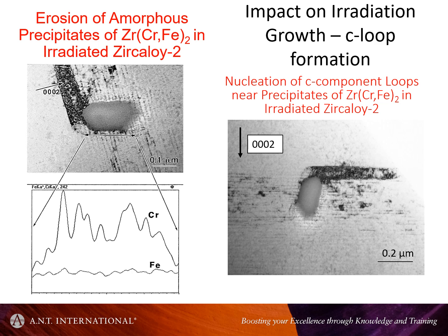But it turned out, to their credit, they reported years later that they found that ion milling created amorphous transformations. Basically, it was an artifact. So just like the hydrides, you have to be very careful about amorphous structures, and be careful that you understand how they were prepared.